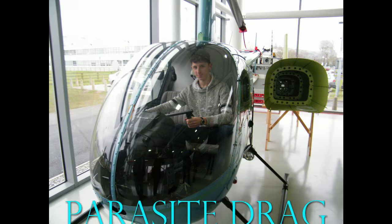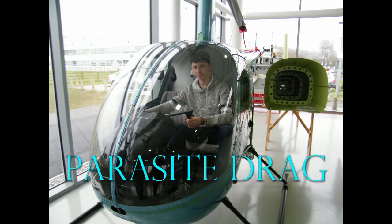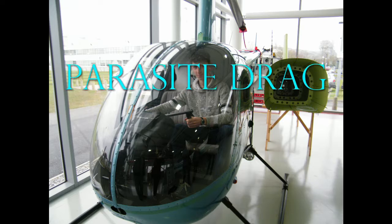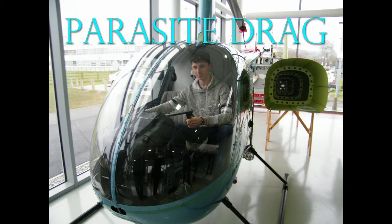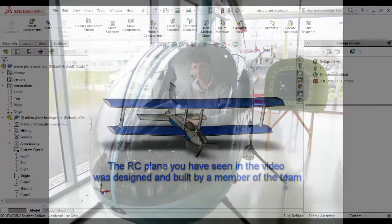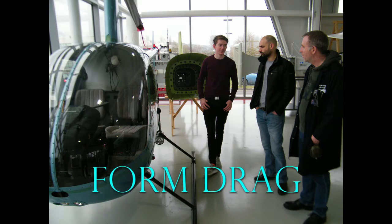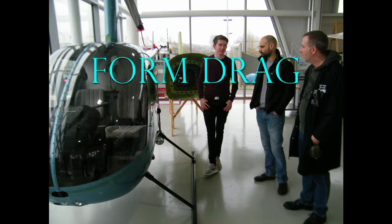Parasite drag is created as a result of an object moving through the air but is in no way associated with the generation of lift. Parasite drag is made up of form drag, interference drag and skin friction drag. Parasite drag largely influences aircraft design, but it is important for a pilot to have a basic understanding of these forces. Form drag is the drag created due to the shape of an object and the airflow around it.